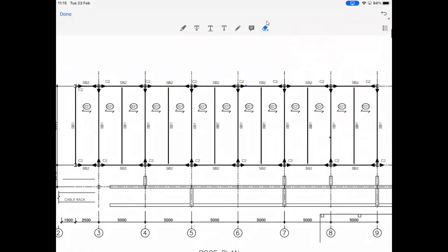Okay. So, you just finished the loading on the beam, and you should say that it's not too difficult. And we have the two sets of beam. The first one are the secondary beams that are laterally braced by the floor system. As I may have mentioned before, you have to find a way to secure the floor to the beam. Okay, you cannot just place the floor on the beam and hope that it would stick.